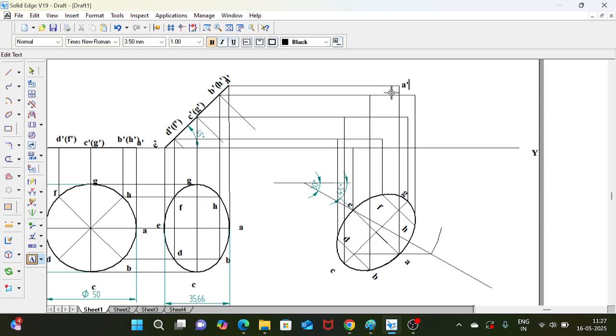So now we have to see where B is. Once you get AB, this will be C. You know the path direction, C, and this will be D dash, and this will be E dash, F dash, like that, continuously it will go like this. Then G dash, then H dash. See, when you are joining the line like this, say this F point meets here, it should end here only. Don't carry the extra projection upward or forward. Then it will be easy to join.